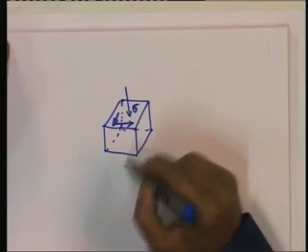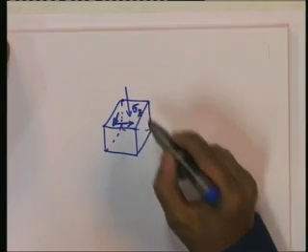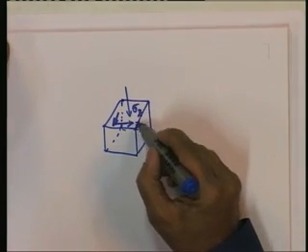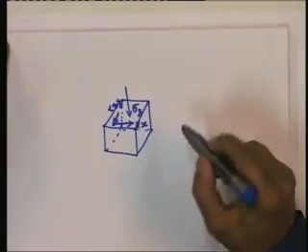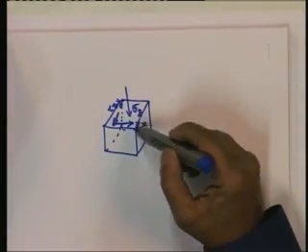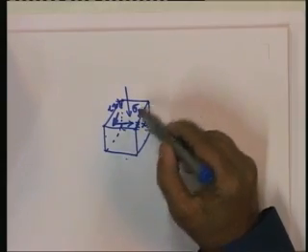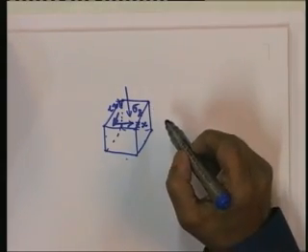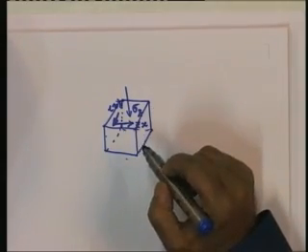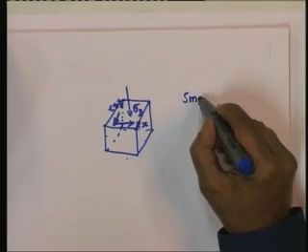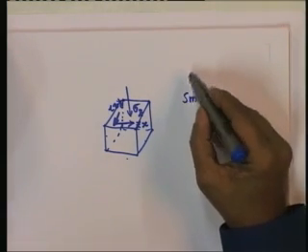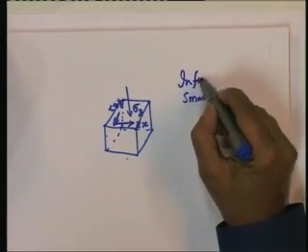This is a normal stress, this is a shear stress in the x direction, and this is a shear stress in the y direction. Like this, there will be three stresses on each one of these surfaces. All these stresses we shall assume to be uniformly distributed over this small parallelepiped. The element is going to be considered to be very, very small. It is infinitesimally small.